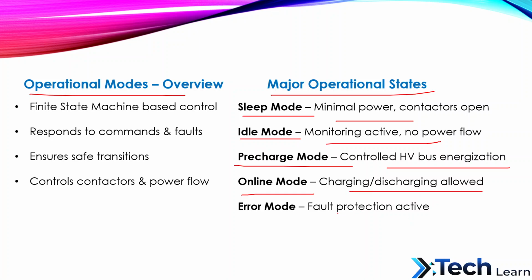Now coming to the error mode. In error mode, contactors are open. Charging and discharging are avoided. The fault codes can be retrieved. The system must avoid endless cycling between error and active states.